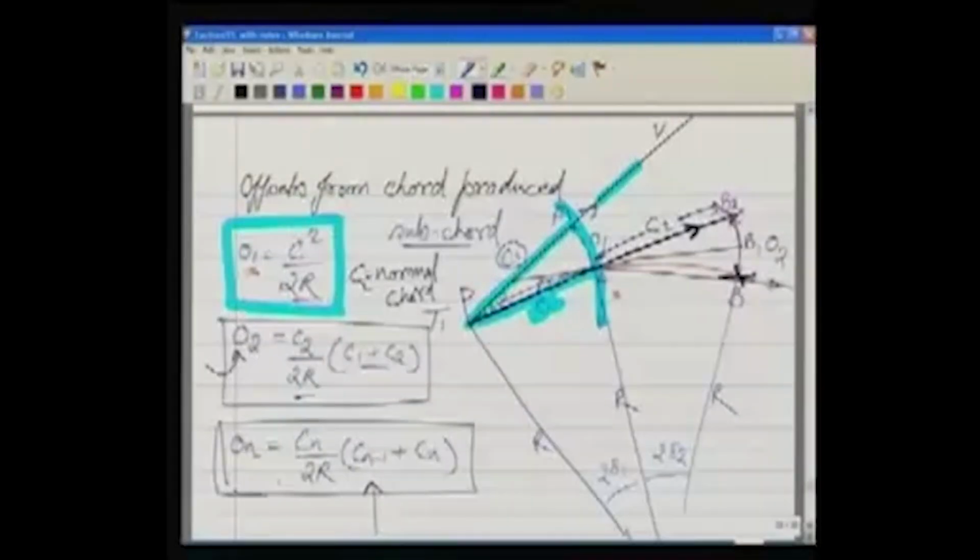For example, C2 we took and an arc, and then along that arc we cut a distance equal to O2, as given here. So this is the general formula for this procedure. If we follow this, we are able to set the points all along the curve only by using length measurement. We are not using any angle measurement still.